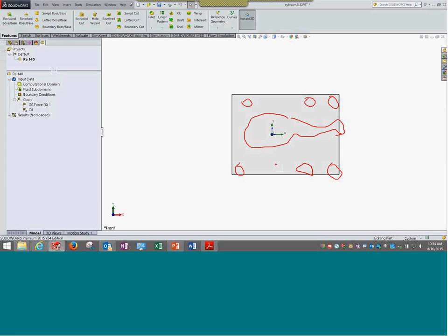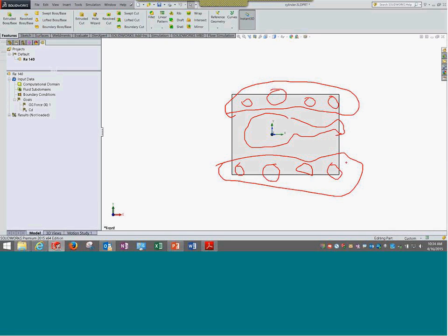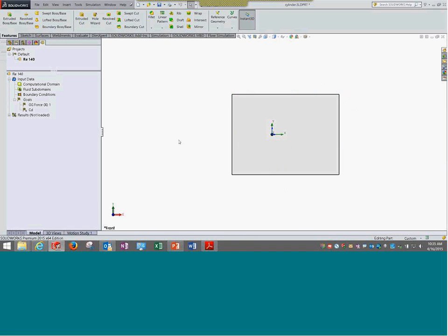So in case of transient analysis, I may not want to continue solving for pressure and velocity there. I freeze the flow over here, so it will not calculate the pressure and velocity distributions, and we can reduce that much amount of calculation. So that option has been given. Use it cautiously.